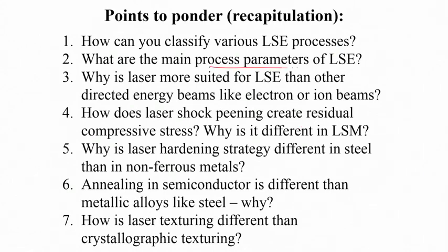The main process parameters are, as I said, the power density and interaction time. And laser surface engineering is more suitable than electron beam or ion beam purely because of the exponential decay of the deposition profile compared to the Gaussian profile of electron or ion beam.